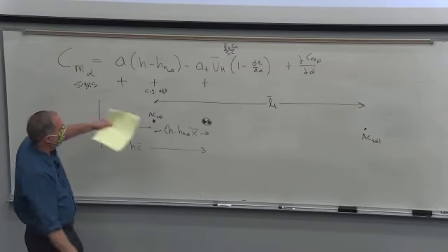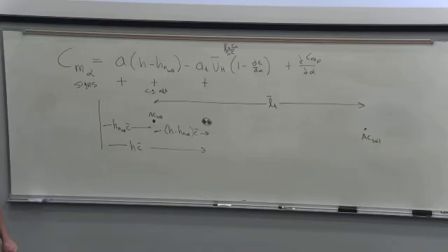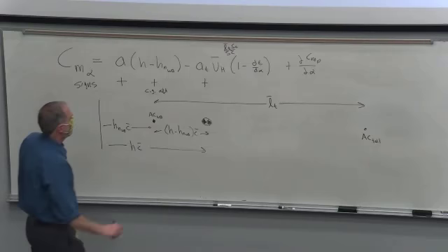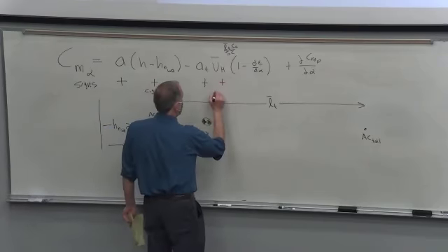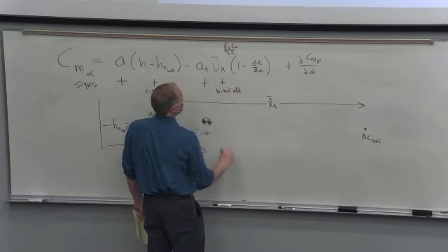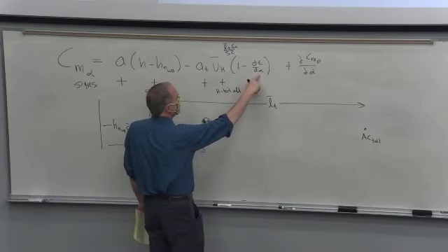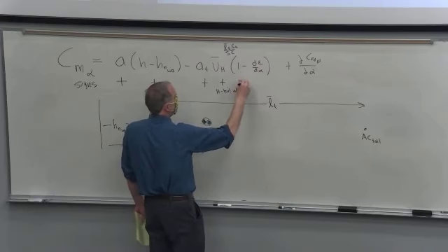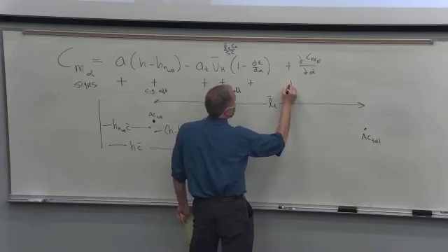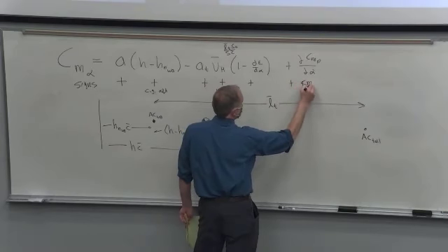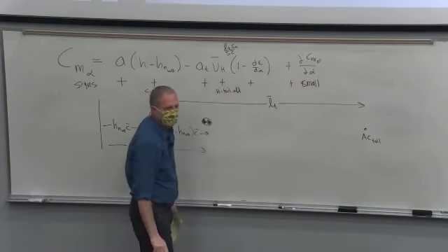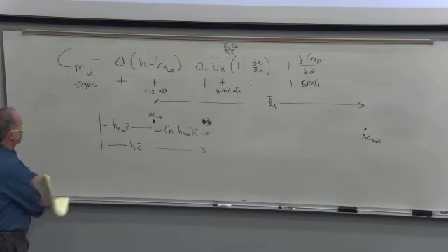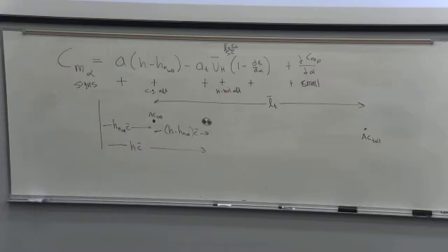If we put the horizontal tail in front, LT bar is going to be negative, right? So this is positive with the H tail aft. And d epsilon d alpha is usually much less than 1, so this is positive. And we're going to just kind of neglect this. This is small. We're going to say that the thrust line is pretty much lined up. So can we make that negative? And if so, how do we do it?